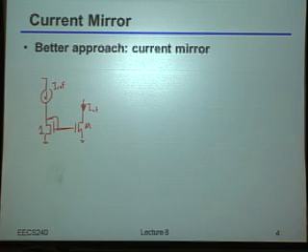But it turns out that 90x% of the time in your analog circuits, creating that current in the first place is usually not so much what you care about. It's more that you care about getting enough current for all of the different blocks in your circuit, or basically creating currents for all the different blocks in your circuit from some known reference value. Okay?